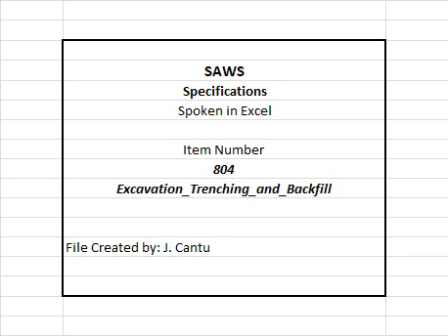equal provisions. B. Payment for such tests shall be the responsibility of the owner, including the material proctor tests and density tests. C. The contractor shall request testing work performed by the owner by notifying the owner of the areas available by station numbers or dimensions and lift numbers. D. The contractor shall provide access to SAWS and to lab to the test area, backfilling test areas and provide associated trench excavation safety protection at the contractor's expense for all depths and lifts.